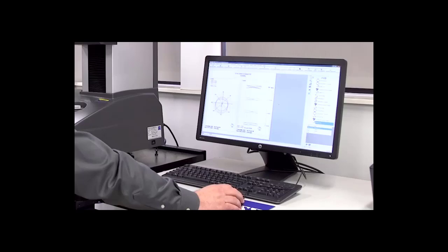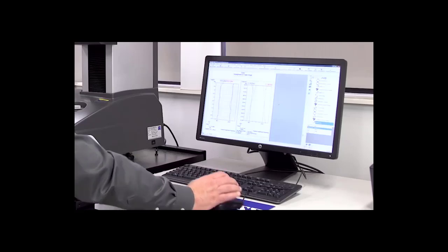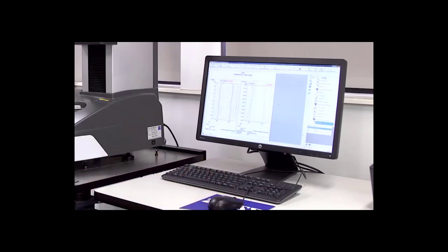Also, from our two traces that we took across the cone with R-axis tracking, we were able to evaluate straightness on both sides of it, and also we were able to compare those two straightnesses for a taper, where in this case we show an included taper of almost 37 degrees.